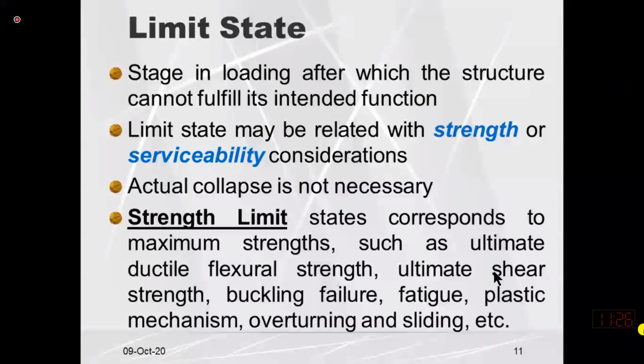So, strength limit state corresponds to maximum strength. Maximum strength may be ultimate strength, shear strength, yielding strength, buckling strength in case of compressive load, fatigue or plastic mechanism, overturning or sliding. Depending upon the applied load, we can put the limit on any type of strength.